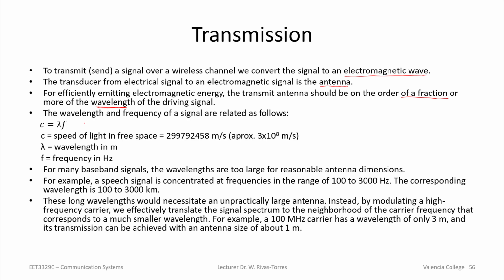If I were looking at the signal on the oscilloscope, the wavelength would be the period, except that when we're talking about transmitting the signal through space, we talk about that same wavelength in terms of distance, so the wavelength would have units of meters, for example.